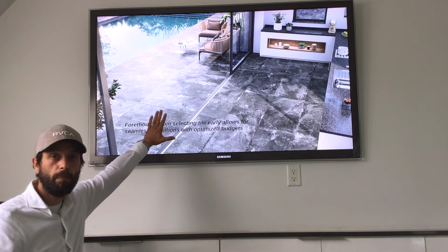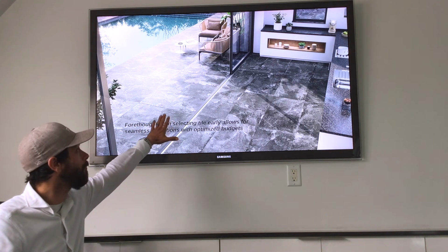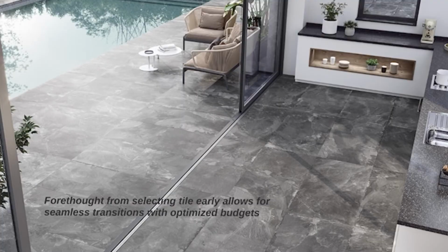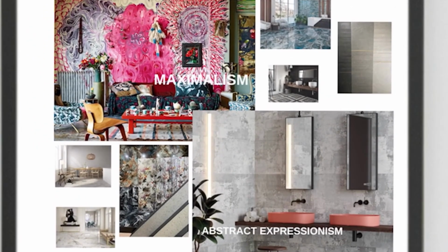The installation goes much quicker and less expensive because we don't have to prep the substrate, we don't have to pour a slab, we don't have to get our tolerances for these large formats so tight in the planarity of our slab. It just lets us do so much. So if you start thinking about tile in the structural design phase instead of the finishing, it makes a huge difference. And we'll get more into that when we get to specs.